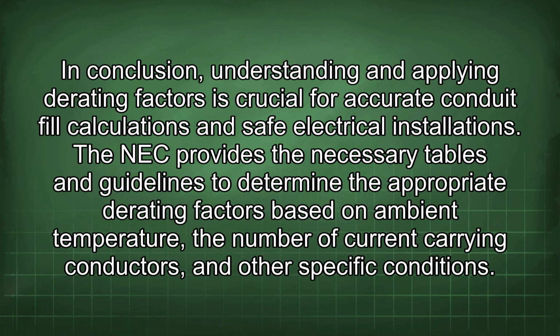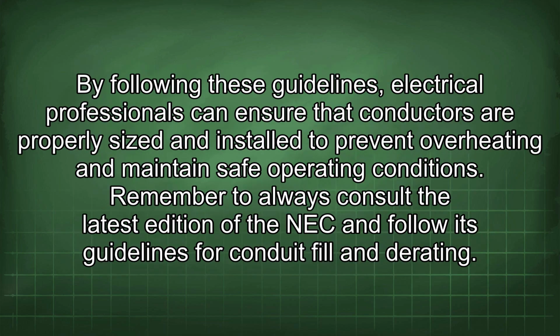In conclusion, understanding and applying derating factors is crucial for accurate conduit fill calculations and safe electrical installations. The NEC provides the necessary tables and guidelines to determine the appropriate derating factors based on ambient temperature, the number of current carrying conductors, and other specific conditions. By following these guidelines, electrical professionals can ensure that conductors are properly sized and installed to prevent overheating and maintain safe operating conditions.